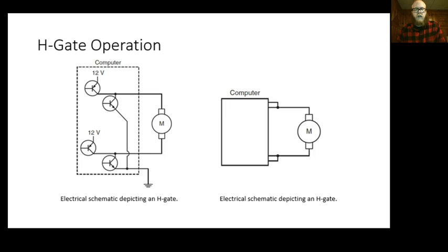No. I'm going to check to see if it rolls up and down, right? Verify customer concern. Still doesn't roll up and down. Is this computer getting the input that it needs to know to roll the window up and down? Well, that depends on the circuit. Maybe it just gets 12 volts on one wire coming into it. Maybe this is connected to another computer and we could go in with our scan tool and see a request. Yes, it wants it to roll down. Okay, we're seeing that on our PID.